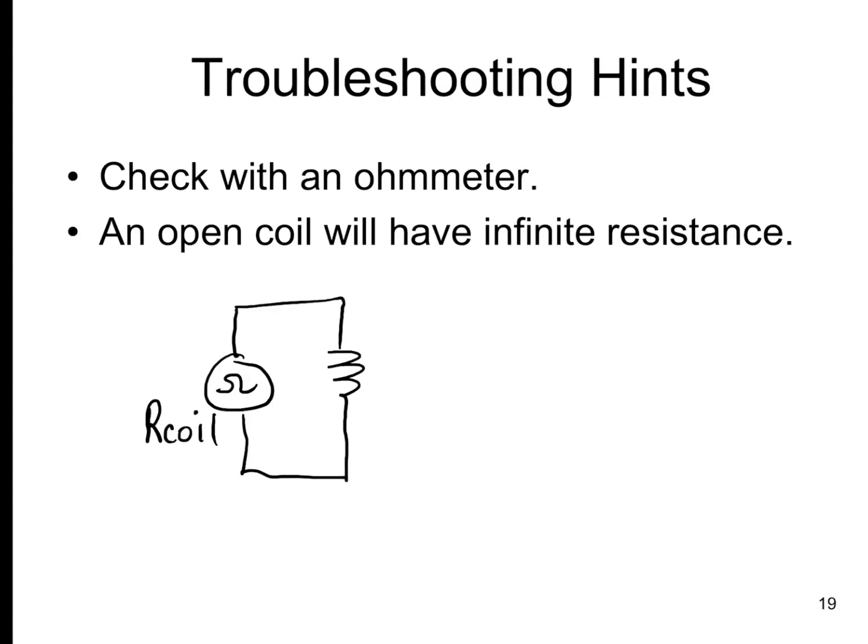Okay, last part here is just saying when you're working with inductors in the lab or anywhere else, you can really, for the most part, get a good sort of prediction if you have a working inductor by using an ohm meter. Because it's just a coil of wire, if you measure it and you have a small amount of resistance, you can be relatively sure you're working with an operational inductor. And of course, what's the most common fault for an inductor is that the power that's being dissipated by the conductor that makes up the coil can't handle it, and you end up with an open.